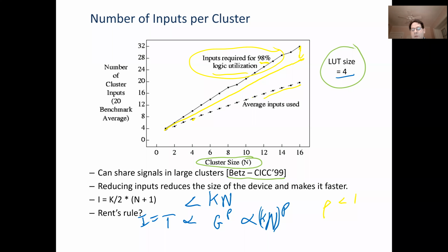And if that's the case, then you'd be better off to say, look, it's okay to only use 96% of them. Most of the logic blocks will still be full, but there'll be some that I can't fill completely because they're from parts of the circuit that don't share as much, they're kind of more irregular. They don't share as many signals. These lookup tables are kind of hard to pack. And I wind up with some logic blocks that I just can't fully pack. If that doesn't happen that often and I saved a fair amount of area, it may actually be a better choice because I could just build more logic blocks.